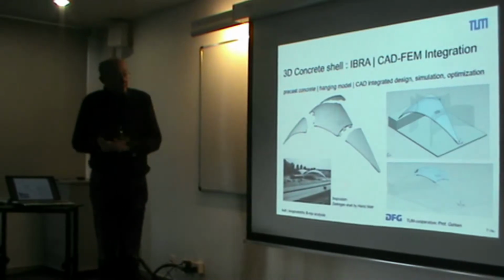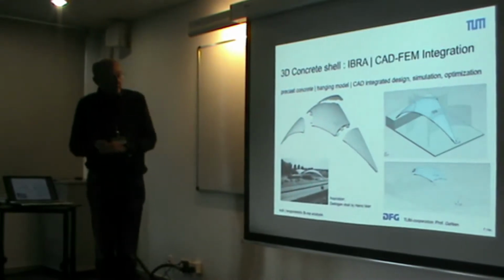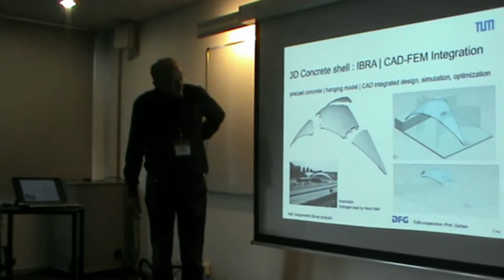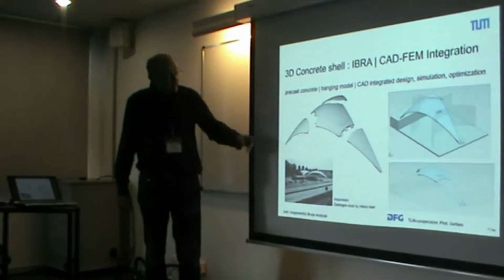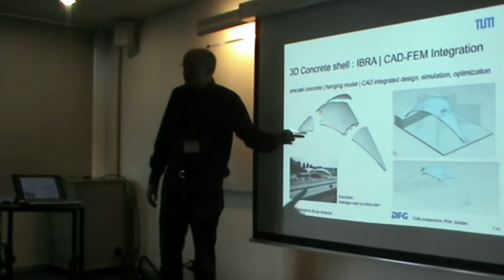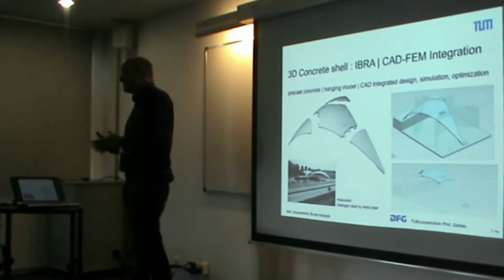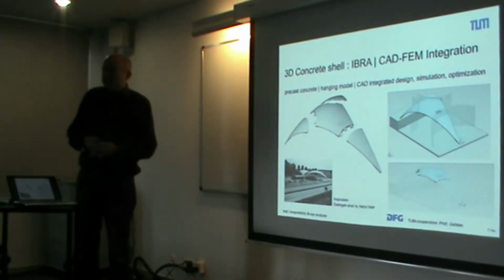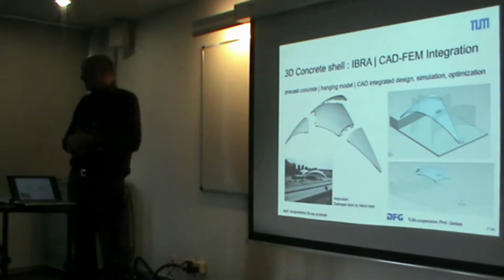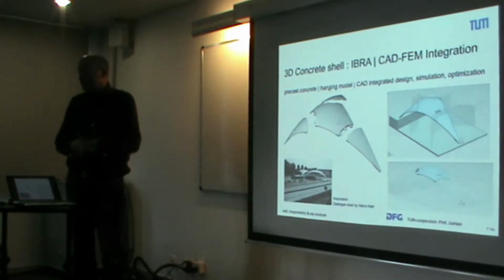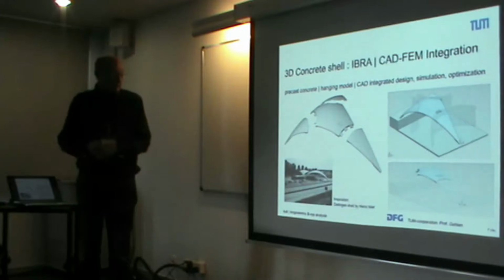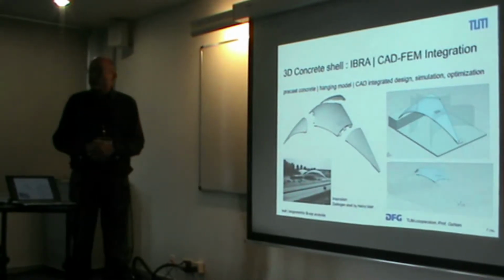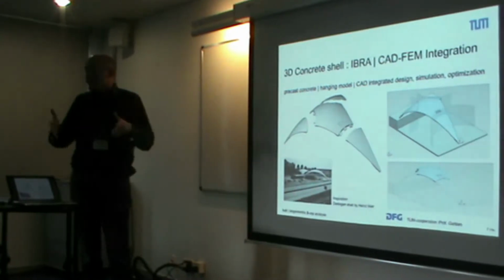That is the outcome of a DFG, German Research Foundation, funded piece of work done by Michael Breitenberger. That's basically a 3D puzzle of shells. So the idea: how can we bring concrete shells back into the actual situation of civil engineering? It's a problem building concrete shells because the formwork is much too expensive, so it makes sense to prefabricate them in smaller pieces, make 3D pieces out of them.